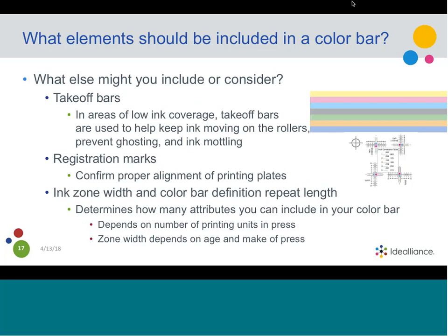Yeah. And Dan, other things that you'd look for? Absolutely. I mean, in addition to those marks which Bruce mentioned, which are very common, some other things you may want to consider adding either to your color bar or around your color bar, namely number one, takeoff bars. These are generally used in areas of low ink coverage. What the takeoff bars do is they help keep ink moving on the rollers, and this prevents ghosting and ink modeling in the image area.